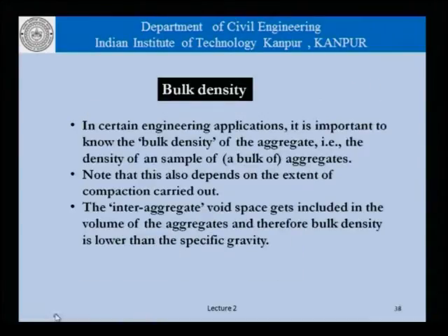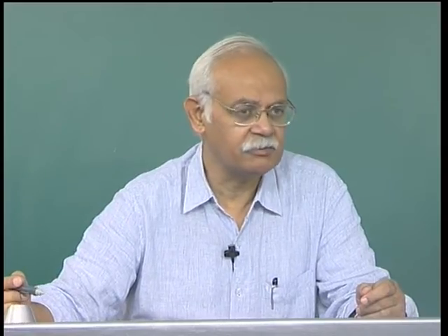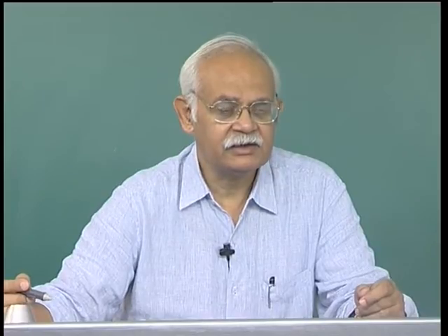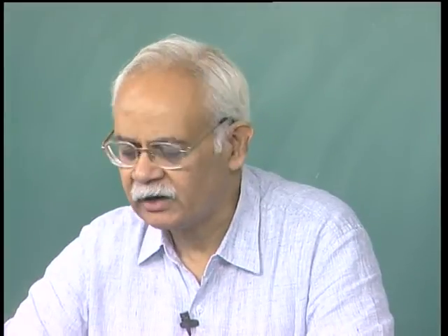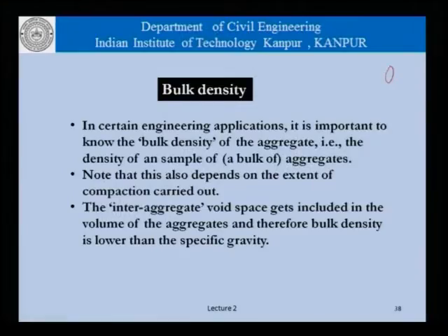Then there is a concept of bulk density. In certain engineering applications, it is important to know the bulk density of the aggregate, that is the density of a sample of a bulk of aggregates. That is, we have these aggregates all over the place, and we want to find out the bulk density, that is all these void spaces in between these aggregates will get included in the volume.